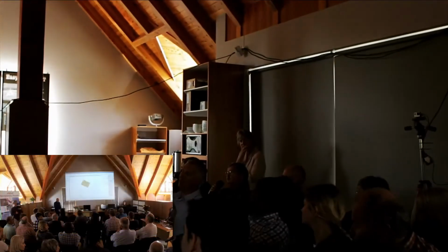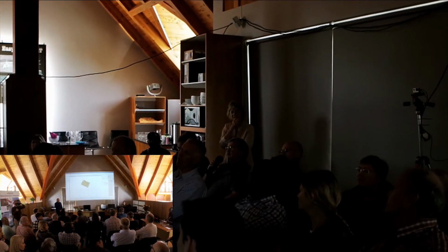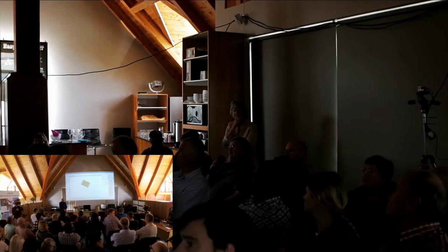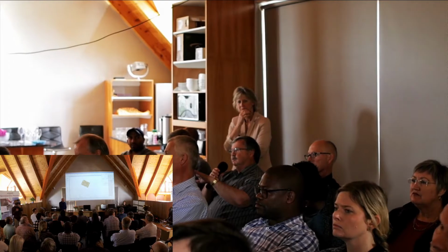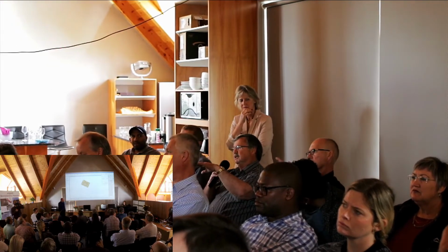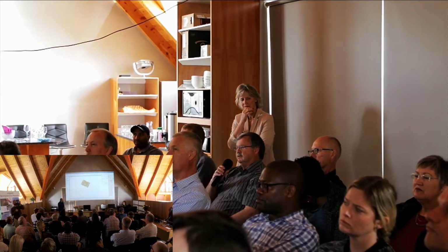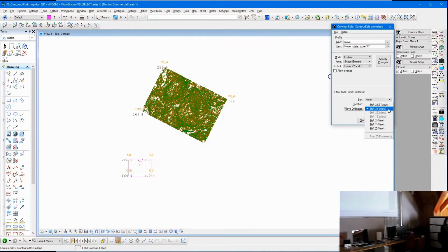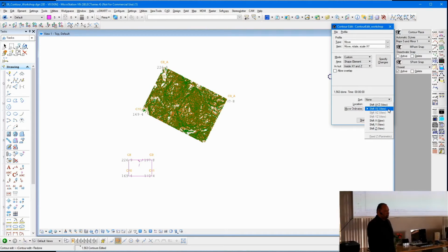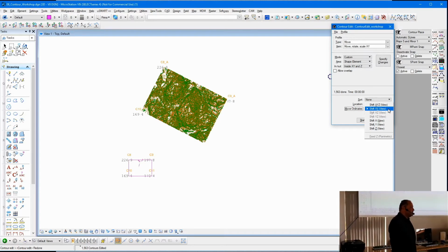When you moved and rotated and scaled, the Z values will then also change. Will the contours regenerate on the different plane? Okay, so it's optional. Very good question. Move ordinates over there. So we chose to just move the X and Y. Move, rotate, scale, X and Y only.